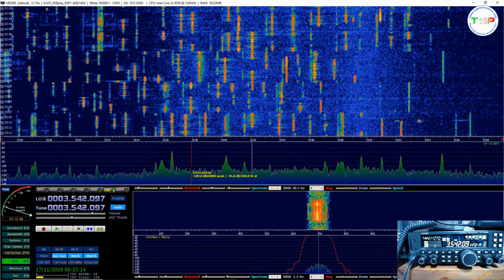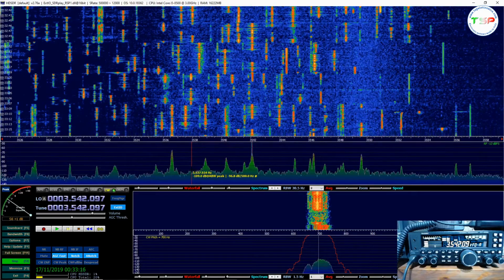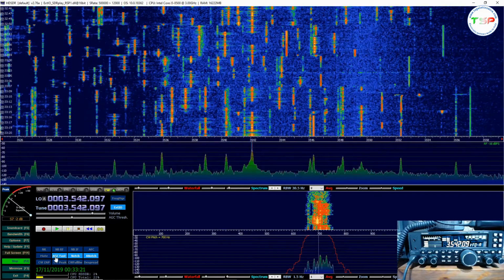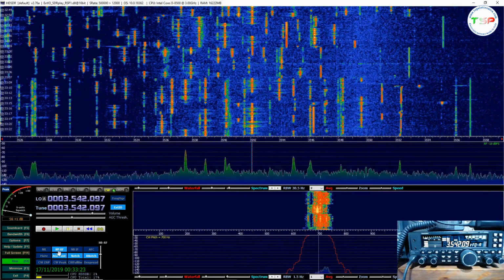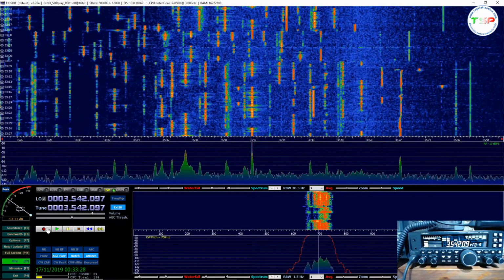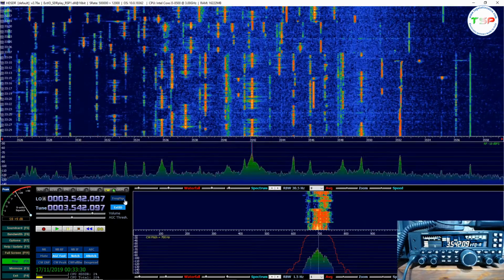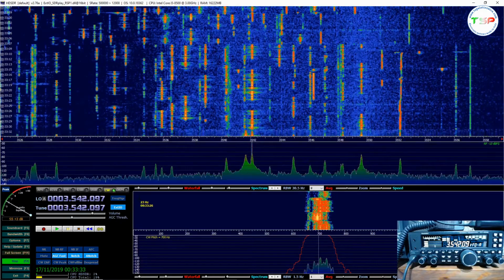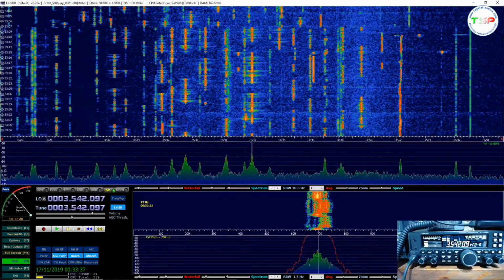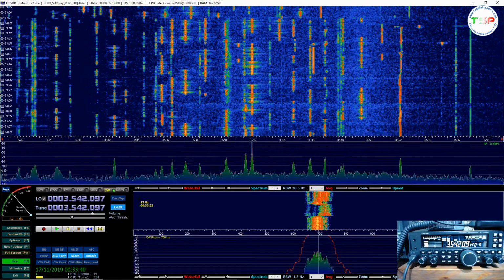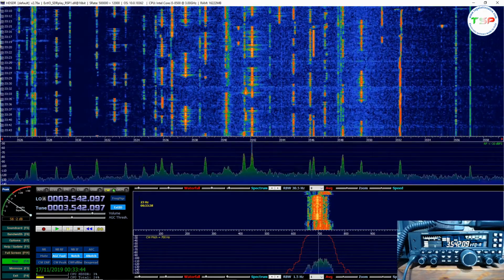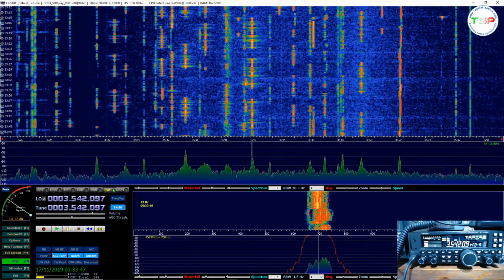You see, very easy. And I can also have a notch, auto notch, and many other features: noise blanker for RF, for IF, auto frequency control. I can even record the signal, the demodulated signal, sorry. Okay, so I guess it deserves a try. You will find the detailed description on our website. You can find the link to our website in the description of the video.